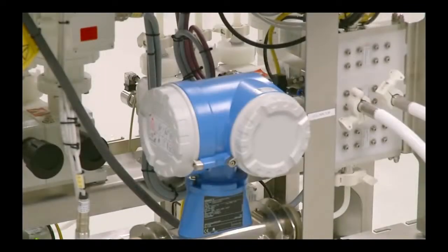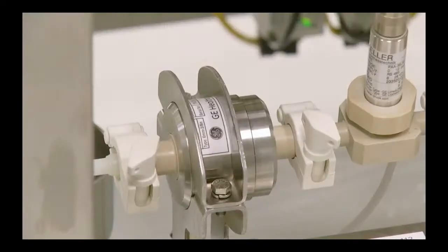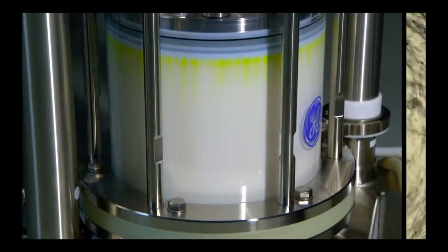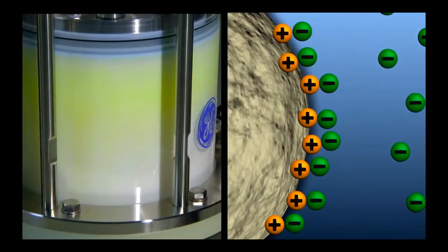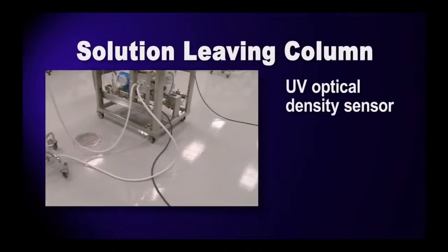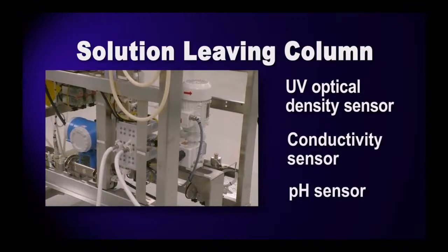After pre-filtering and before the column, the lysate passes through a flow meter and an air sensor. Then, as the lysate passes over the resin beads, the negatively charged protein binds to the positively charged beads. The solution leaving the column passes a UV optical density sensor, a conductivity sensor, and a pH sensor.